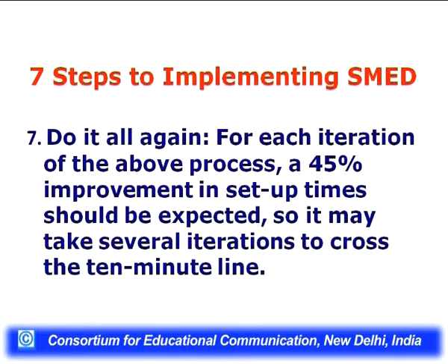In this step, we are saying that whatever procedure we have made so far should be tried a number of times. Each time we want to reduce the time, with close to 40% reduction in setup time, and keep on doing this till it is stabilized at the minimum level, and that is the time we are going to assign to the setup, to the changeover.